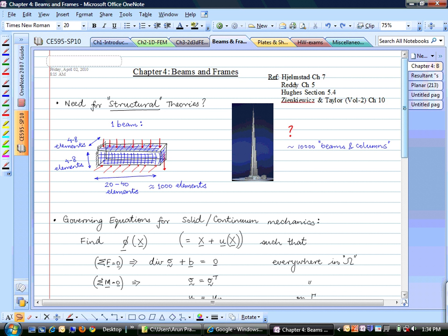If you want to model something like a joint, and model the bolts as well, look at the example in the Abaqus manual, I think Appendix C, which has a hinge joint. That example you should definitely go through. It is very similar to your lap joint problem.